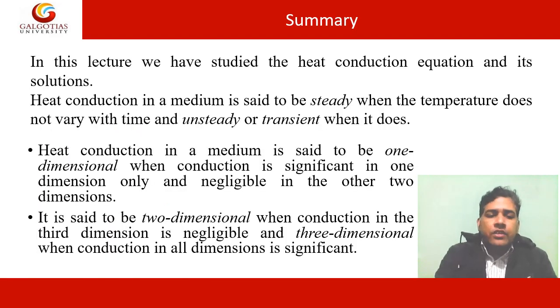In summary, in today's lecture we discussed Fourier's law of heat conduction in detail. This is the first lecture in which we started our derivation of the heat conduction equation using Fourier's law. In the next classes, we will derive a full-fledged equation for heat conduction. Conduction in a medium is said to be steady when the temperature does not vary with time, and unsteady or transient when it does.